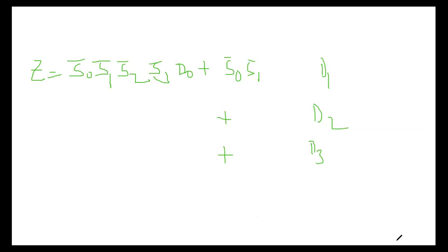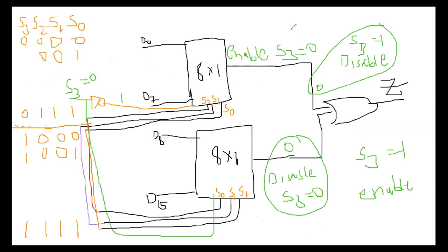Following my students, like that we can design a 16x1 MUX by using 2 8x1 MUX. What additional logical gates are required here? The 2 8x1 MUX and 1 OR gate and 1 inverter. That only is explained in the theory.